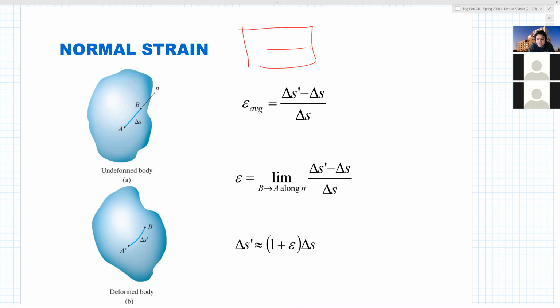which becomes dl, right? Now, in general, L is a good variable. I'm going to start using L, but in general, what the book does and Hibbler does consistently is that for any length along any axis, they use the path length. That's why they use the variable S. Doesn't matter, you could use whichever variable you want, but S is the general one, because look at what axis it's doing. If it's not deformed, it's the N axis. I could call it X, Y, Z, P, doesn't matter. They call it N.